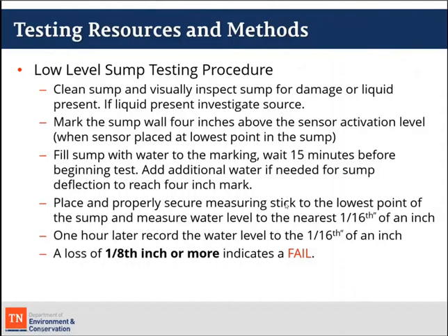liquid source is, whether it be surface water flow or groundwater intrusion. You'll want to make a mark or measure up on the sump wall 4 inches above the sensor activation level. So obviously you want your sensor placed at the lowest point of the sump. So in reality, you're probably going to be looking at 4 to 5 inches above the bottom of the sump. And you'll want to fill the sump up with water to that 4-inch mark. Wait 15 minutes before beginning the test.